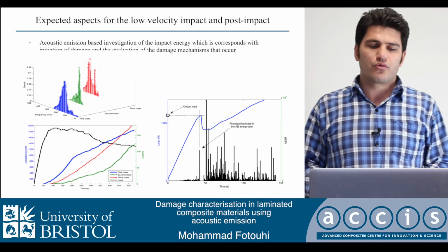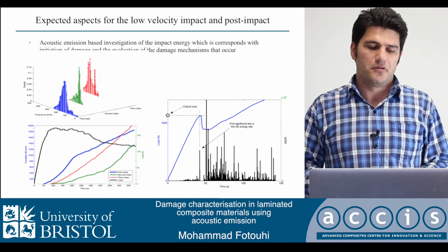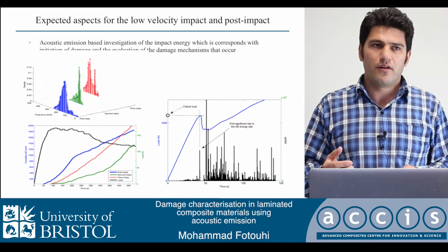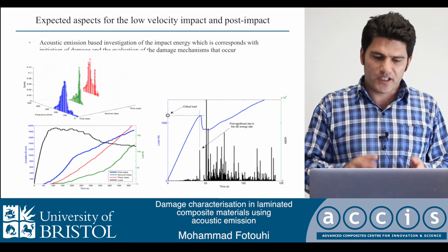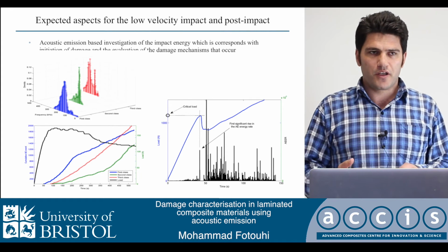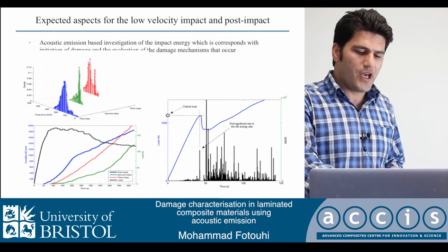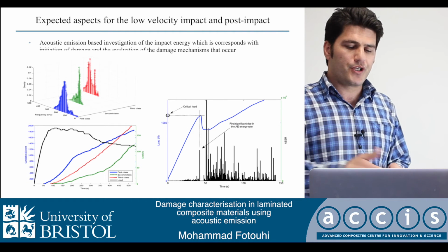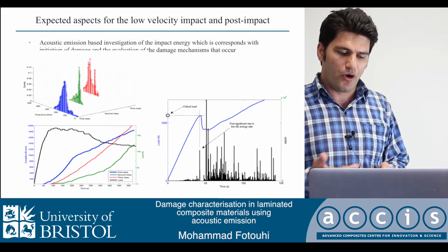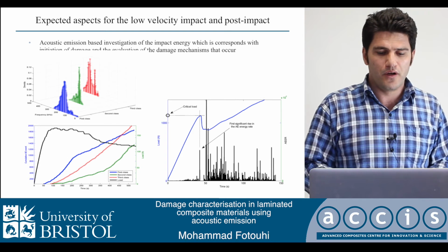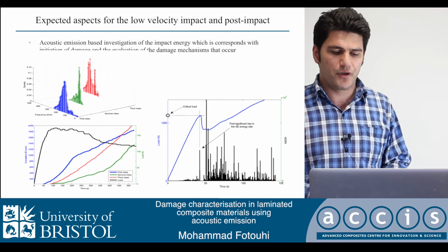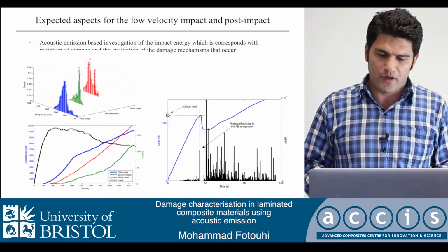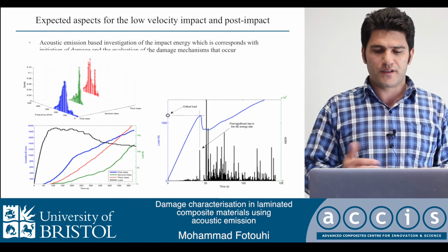Blue is related to matrix cracking, which starts sooner, and it means that our first failure mechanism in this case was matrix cracking. Later, we have fiber breakage and debonding, which happen together. But the number and the percentage of these damages are also different. In this way, with this method, we can characterize them.